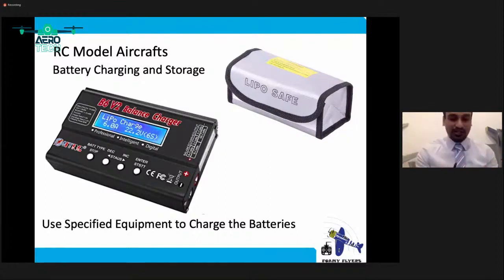So you can basically plug this in and check the battery levels of this particular battery. Now you can see the number 1 cell is this much, number 2 cell is this much, number 3 is this much, and number 4 is this much. So all in all, it has this much power. Because of this COVID situation, I have not been able to use this battery for a long time. Now it has started a bit of a puffing effect, which is not a good sign, because it has to be discharged if you're not using it.